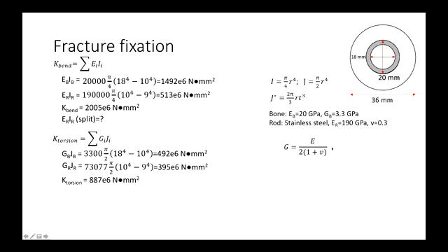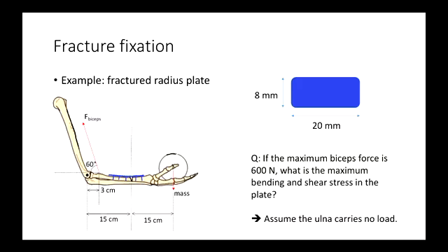And then you add those together and you get the torsional stiffness of the intact rod, so no split. And then if we put it into the formula on the previous, so this formula here, for a split, we end up with the rod's torsional stiffness being 1.5E6 compared to 395. So putting that split in has made it so much weaker. Right? Okay, so this is another example.